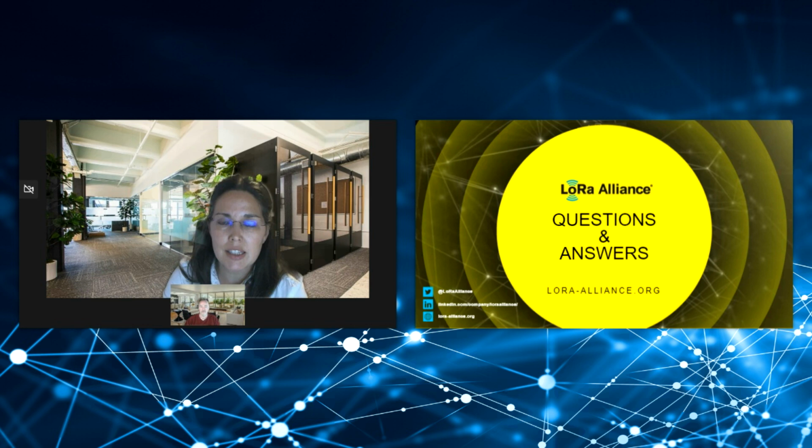Important here for the setup on the gateway side is that you should always use a gateway or a setup with all channels support. So this means for US, for example, you need a 64-channel setup in order to be able to get all join requests sent by the device. Because the goal of this testing is to ensure that the device follows the limitations already defined in the LoRaWAN specification. So it's important to ensure that the gateway is able to receive all the join requests sent.